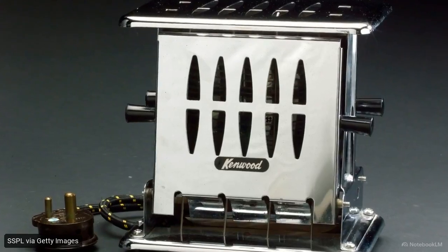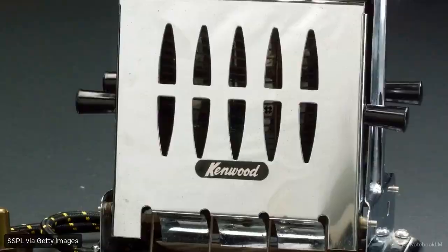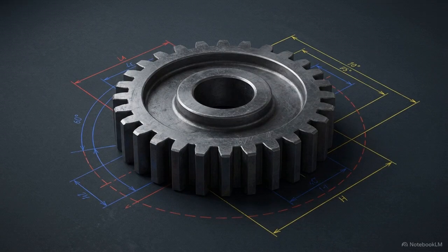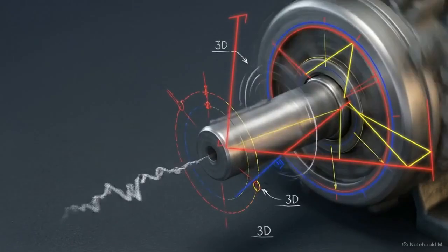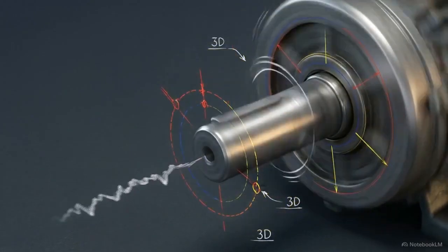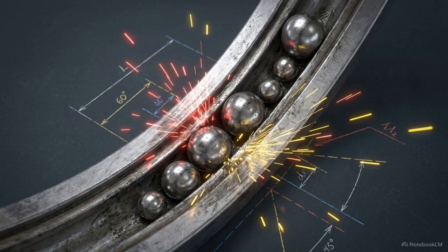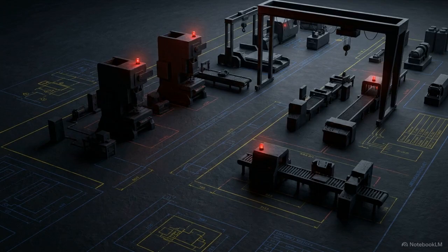A toaster stays hot even if the power technically pulses on and off 100 times a second, but applying that same pulsating power to heavy rotating machinery is a mechanical challenge. It forces the physical driving power of a massive motor to drop to nothing 100 times every single second. This electrical pulse creates severe mechanical consequences. The motor experiences uneven torque, leading to vibration and metal fatigue in the shaft and bearings. You cannot build a heavy industrial economy on a system that constantly turns itself off.